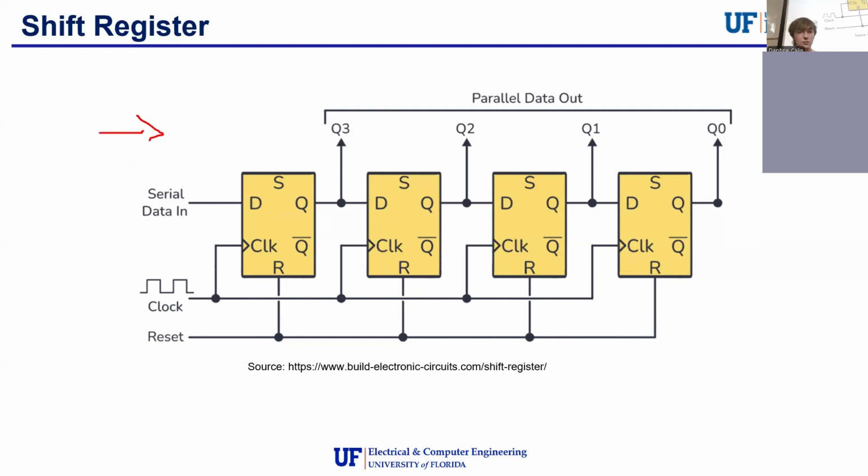If we have a number come in like 1010, the clock is going to cause this output to be shifted just using the logic of D flip-flops. So it'll be 1 0 1 0, and then the input bit will be a 0, unless we use S or R to change the specific input bit. So this is how a shift register usually works, and it's what I was thinking when going into this lab.